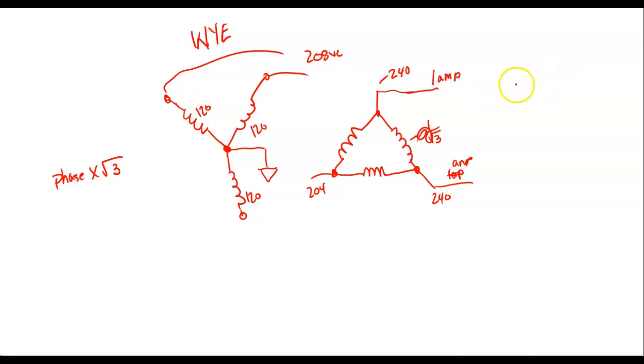Let's bring it on the primary delta. So what they can do is their transformers can actually be rated lower than the current they're actually getting out of it. But we have no ground. So this is why on your power poles you'll see three lines, right? And you won't have a ground. When they come into the plant though, we want to have a common or a ground, and also we want 2 voltages.